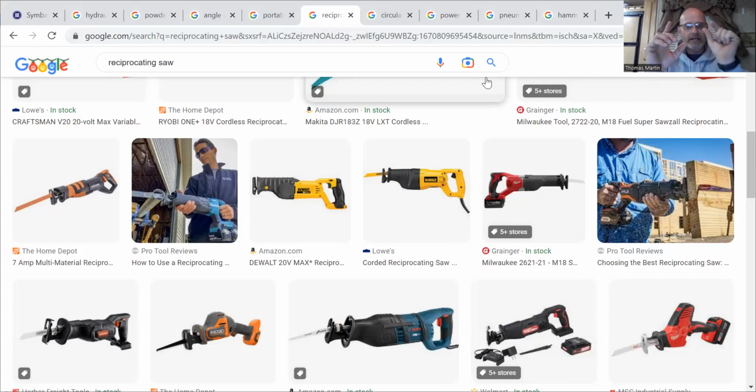There's a 1-inch gap between the outside of that block and the brick. The brick is 4 inches. So 8 plus 1 is 9, plus 4 is 13 inches. So if I have a drill bit that's longer than 13 inches, I need to be mindful to make sure I don't have someone leaned against the wall on the backside or something like that if I need to drill that hole all the way through.